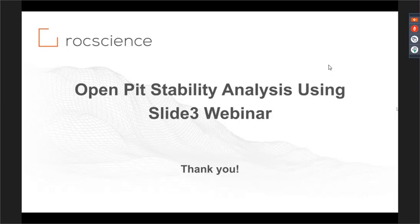We'll be sure to send a reference list with this webinar, but I can say that complex hard rock mines up to 400 meters deep have been successfully modeled in Slide3 to back analyze failure mechanisms observed in the pit. Those failure mechanisms and critical slip surfaces have been validated using the overlay of monitoring data that you can readily import into Slide3 and RS3 software.